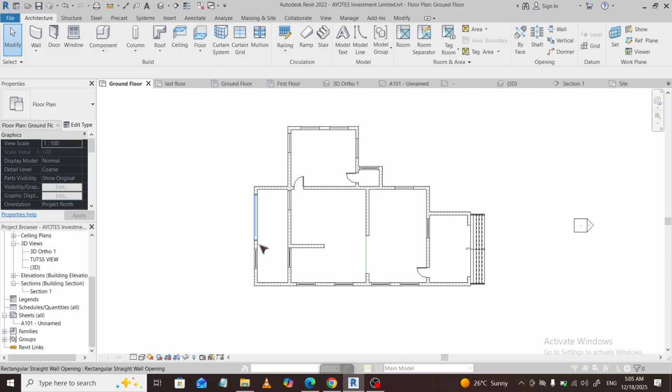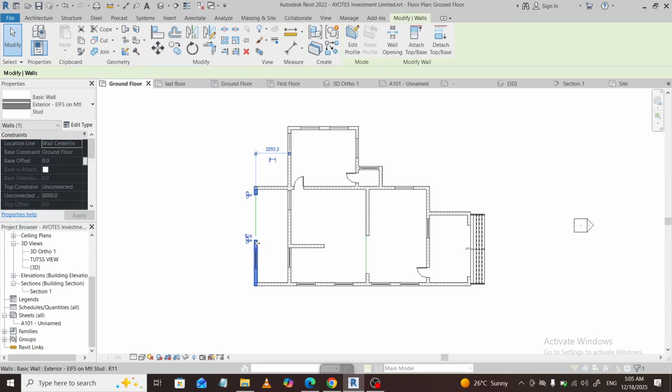If you need the bottom of the opening to align with a level or a finished floor, snap directly to that reference while placing the rectangle. You can also drag the grips to nudge the sketch into position. Keep an eye on the context. Structural walls, finishes, and adjacent elements may dictate minimum clearances or placement rules. If you see the rectangle turn red, it's a constraint or overlap warning. Simply adjust the corners until the sketch is valid.